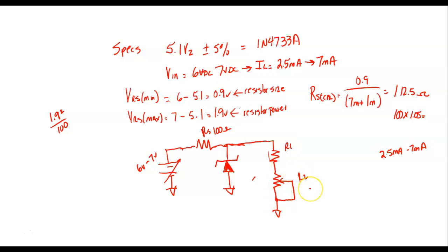First of all, why a 100 ohm resistor? Because if I put this with this rheostat, I could adjust this all the way up here, which would put 0 ohms, and would short out my power supply, and it might burn up my resistor. So instead of my resistor dropping a maximum of 1.9 volts, it could be dropping a maximum of 7 volts. Everybody okay? This makes sense.